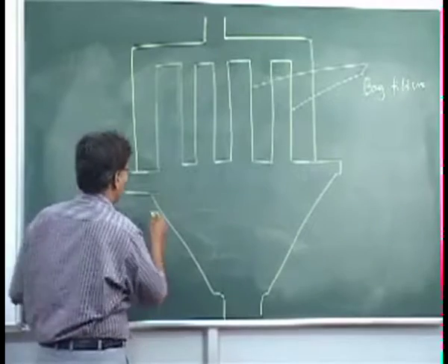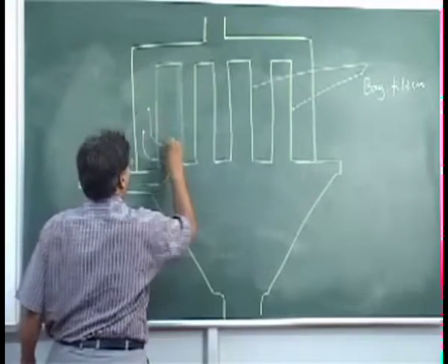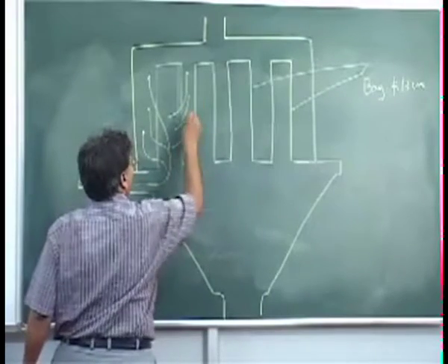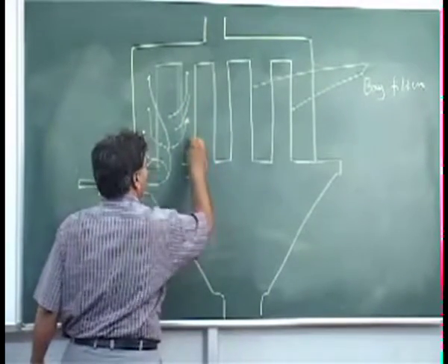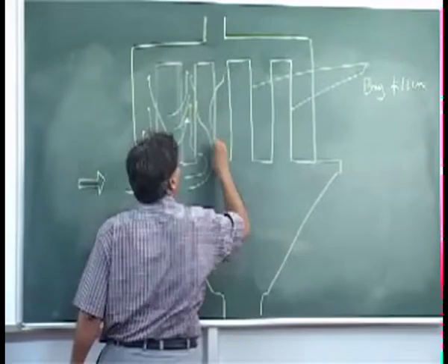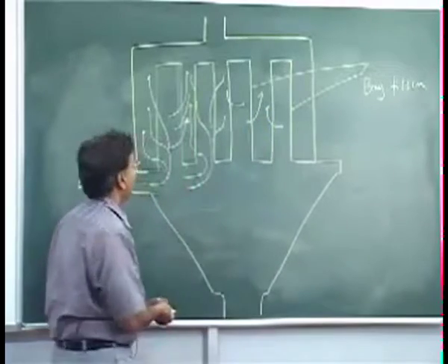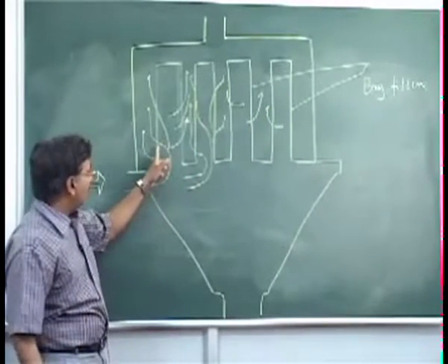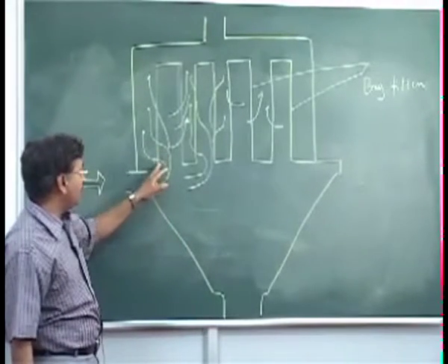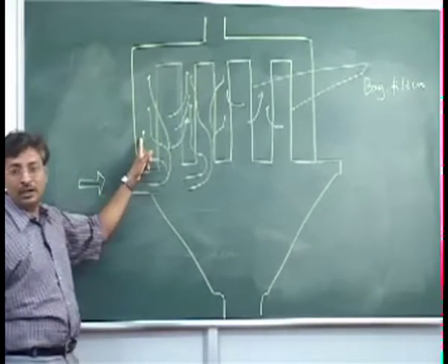and the gas has to pass through, same way from here, same way from here. This gas goes on like this. Similarly from here, here. See? So what will happen? This is your fabric filter, like cloth, a special kind of cloth, and so the particles will be stopped here because of some of these mechanisms, and your clean air will come out.